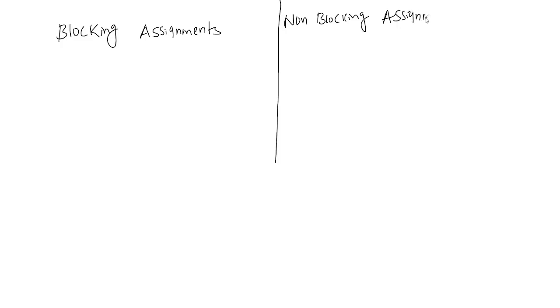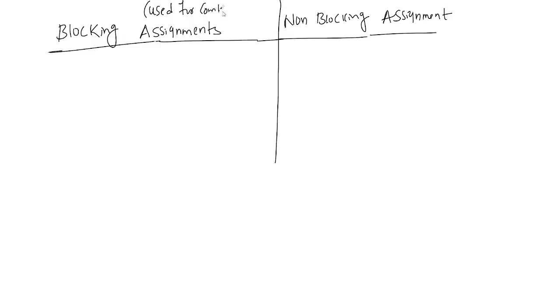Non-blocking assignments. So what are these blocking assignments and non-blocking assignments? I'll tell you. Blocking assignments are mainly used for designing combinational circuits, and non-blocking assignments are used to design sequential circuits.